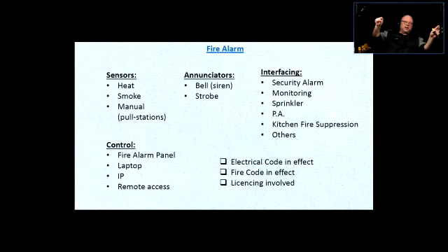If there is a fire, the fire alarm triggers that input or zone, which is programmed as a fire alarm zone, and the security alarm senses that and makes contact with the monitoring station, indicating that there's a fire. And then there are certain procedures: if that zone is triggered, the monitoring station has specific instructions of what to do.